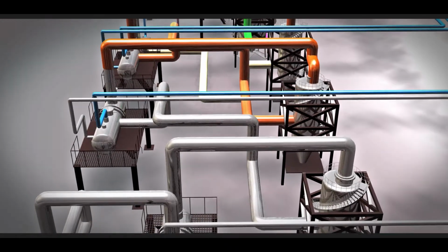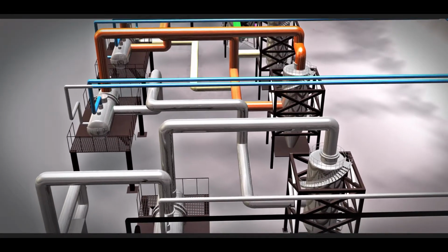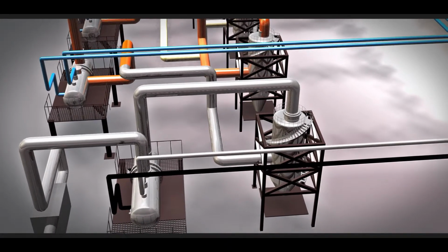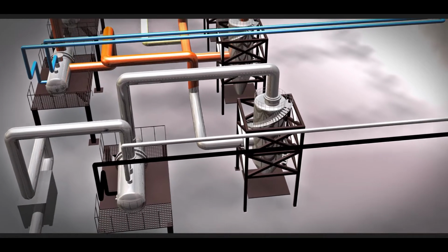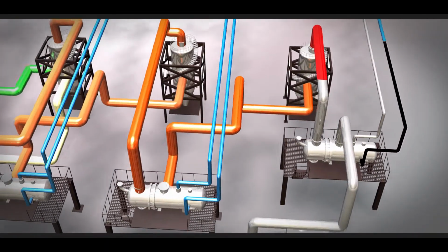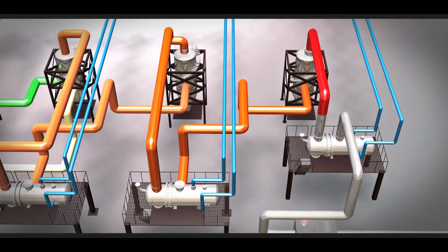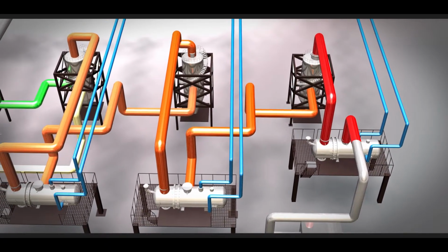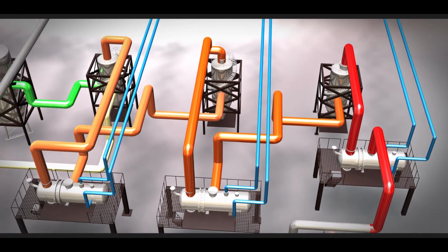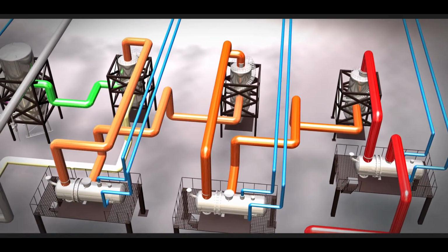In reactor 2, more conversion happens and more CH4 is produced. Temperature is lower than reactor 1 (250 C). Again the product of reactor 2 is divided into 2 streams, one recycle and one product which goes to reactor 3. In reactor 3 an almost pure CH4 is produced.